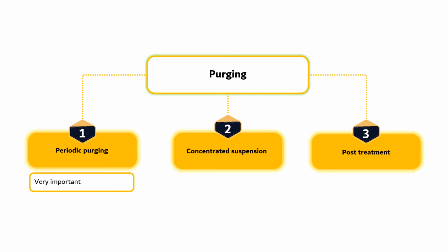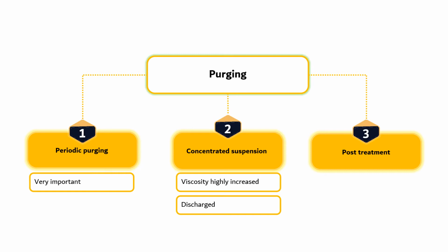Rapidly pumping this suspension, which is necessary to sustain cross flow, is increasingly difficult as its viscosity greatly increases. As a result, the concentrated suspension must be discharged even when it contains much more liquid than a conventional filter cake. Hence, microfiltration may be followed by a conventional filtration or centrifugation to separate completely the insolubles from the solution.